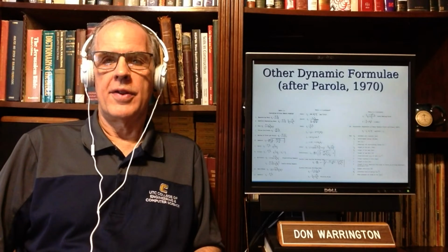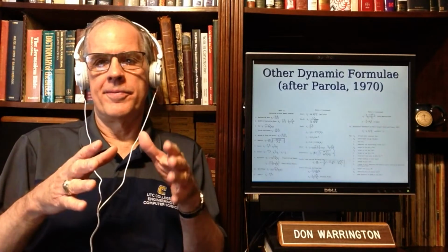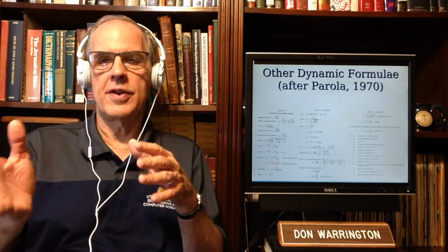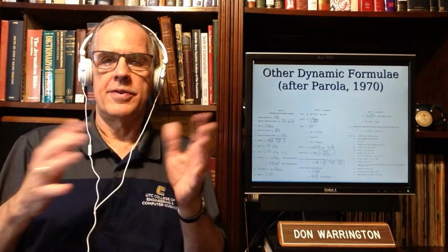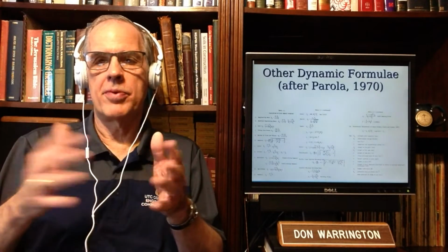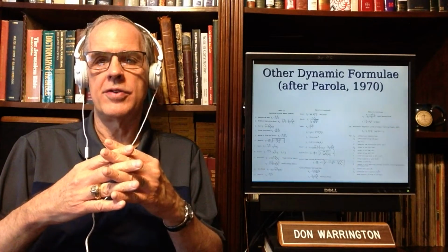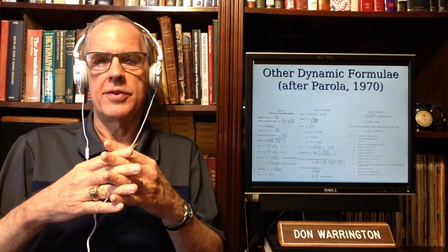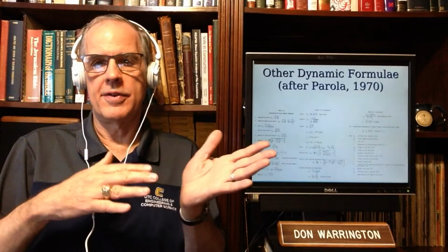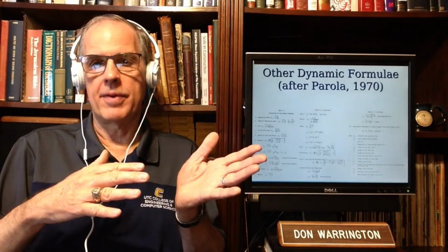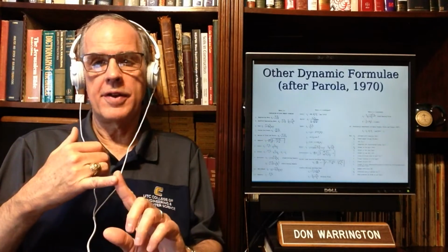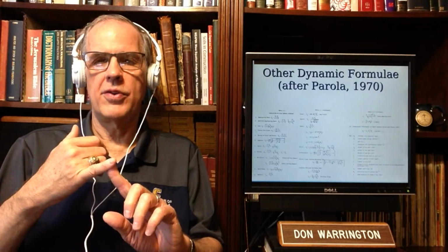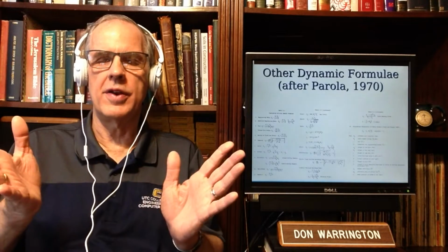So getting from relating the dynamic capacity, using a dynamic method, to a static method has a lot of inherent problems in it, not the least of which is that the soil doesn't respond in the same way to static loading as it does to dynamic impact loading. You've got velocity effects, which you don't have with static loading, at least not much, because there's really no such thing as real static. All loading is in time.